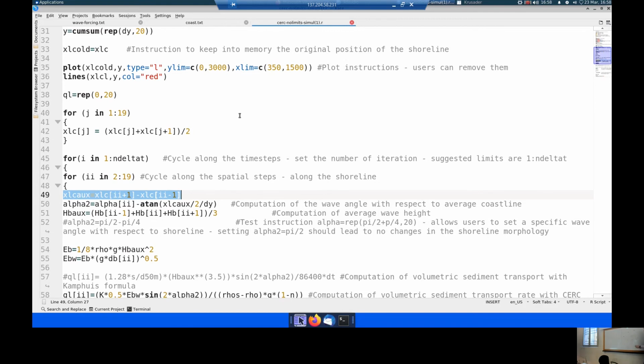Now, I want to compute the angle between the wave and the coastline, the wave direction and the coastline. Very good. So what I could do is to take these 2 points, compute this angle alpha 2, alpha 1 was called in my sketch, and then I know this angle alpha, and then I can compute alpha 2, which is, let me indicate it here. This one.